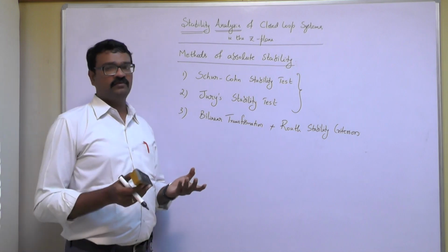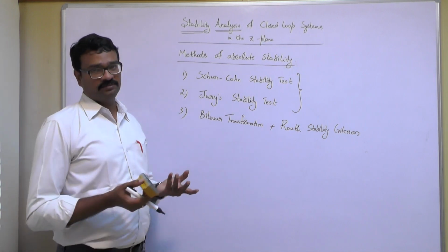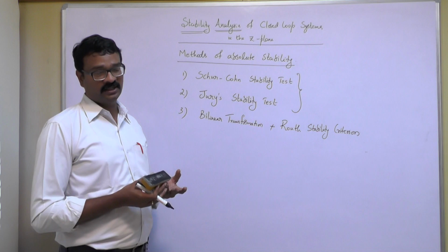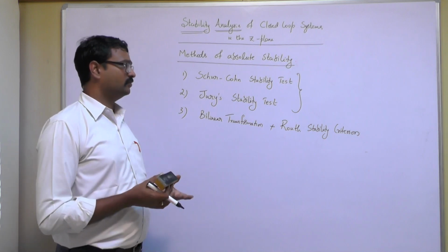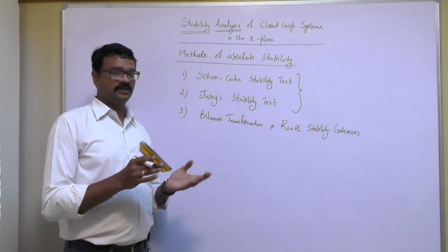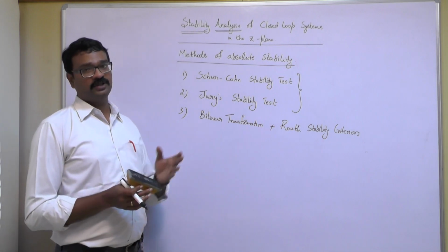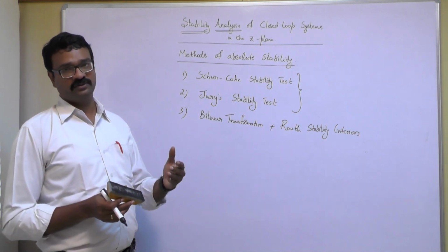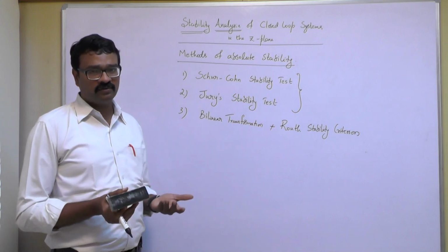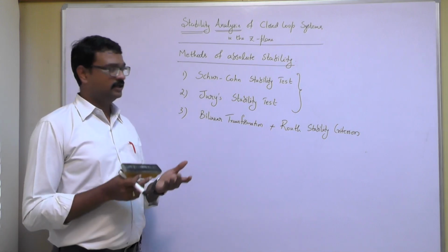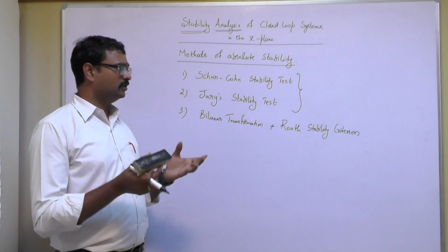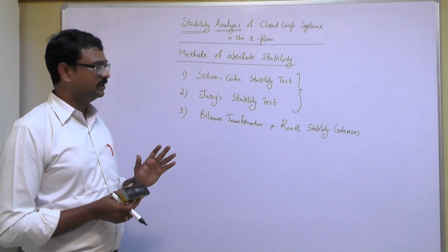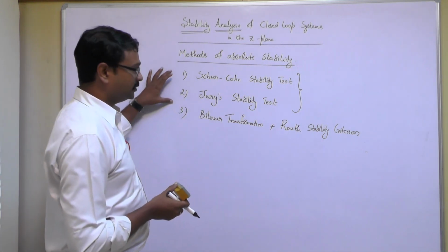And we only require whether the system is stable, unstable, or marginally stable. We don't require the location of the poles in the stability analysis. Only when we are going to transfer the poles from one place to another, trying to make the system even more stable, will we require the location of the poles. But here, we don't require any location of poles for determining the stability. Only the number of poles lying inside, outside, or on the unit circle will be sufficient for us to determine the absolute stability of the system.